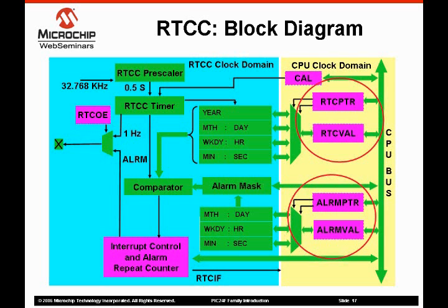The RTCC also includes a periodic timer adjust function to allow the user to calibrate the timer for specific oscillator sources. This function allows the specified number of counts to be added or subtracted from the prescaler every minute. The calibration factor is determined by comparing the timing of the RTCC with a known clock and calculating the required adjustment. The use of the periodic timer adjust function allows the RTCC to achieve 3 seconds per month accuracy.